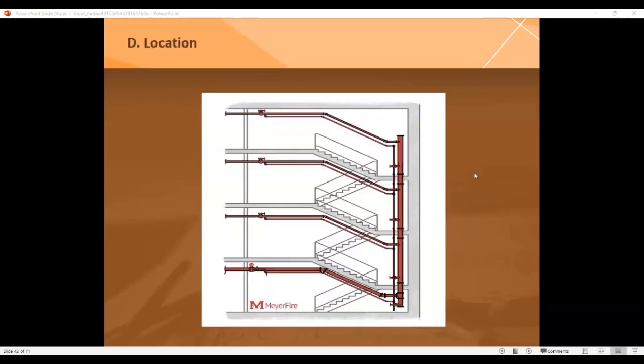In group H and I occupancies, outlets shall be located as follows: one on each side of the stage, one at the rear of the stage auditorium, and one at the rear of the balcony. Where occupant loads are less than 500, the above requirements may be waived, provided that portable fire extinguishers of appropriate capacity and type are installed within easy access from the said locations.